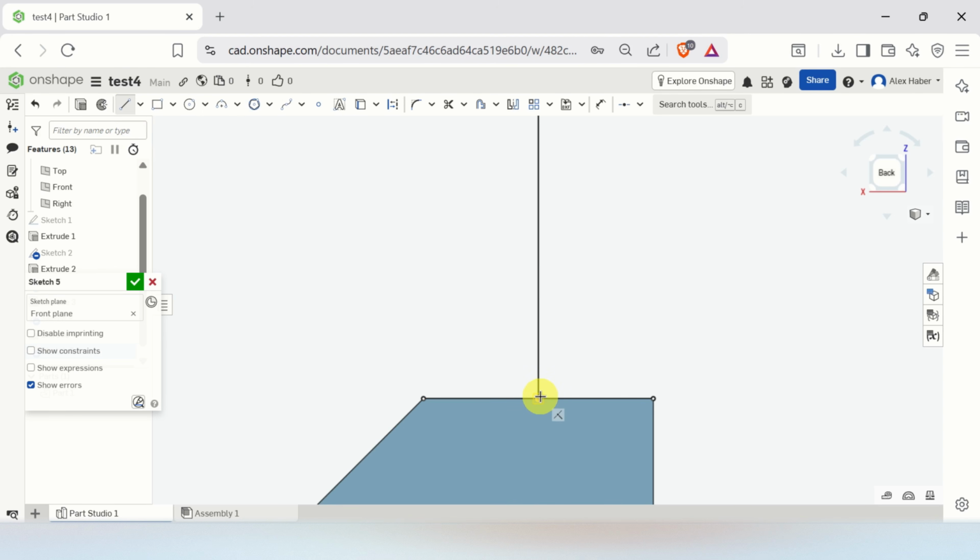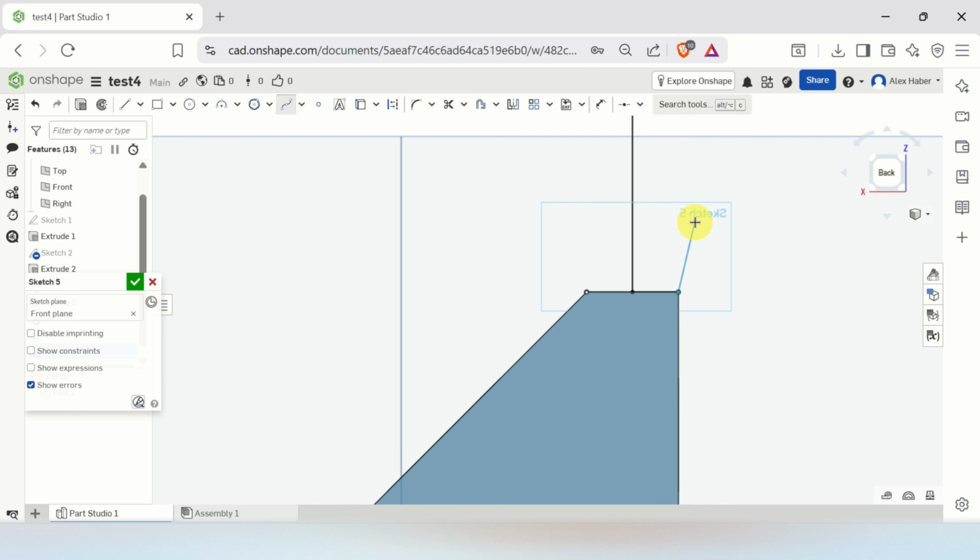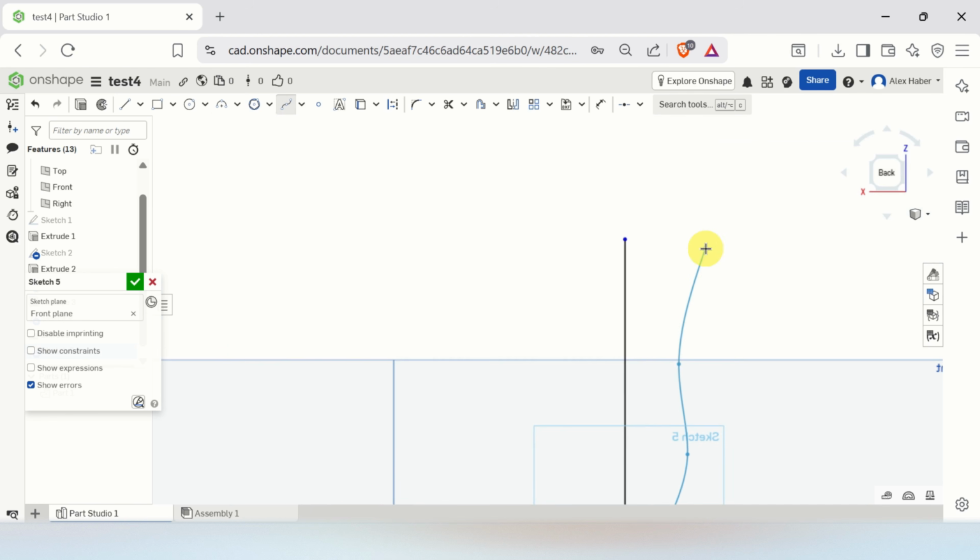First of all, click here to create a line from here to here, and then press escape. Next, let's create an additional thing. Let's create a spline by clicking here, then here, here, here, and finally let's click here to close the spline, and then press escape, and here's our spline. Now you can modify the shape of this spline. Oops, let me now Control Z to erase this.